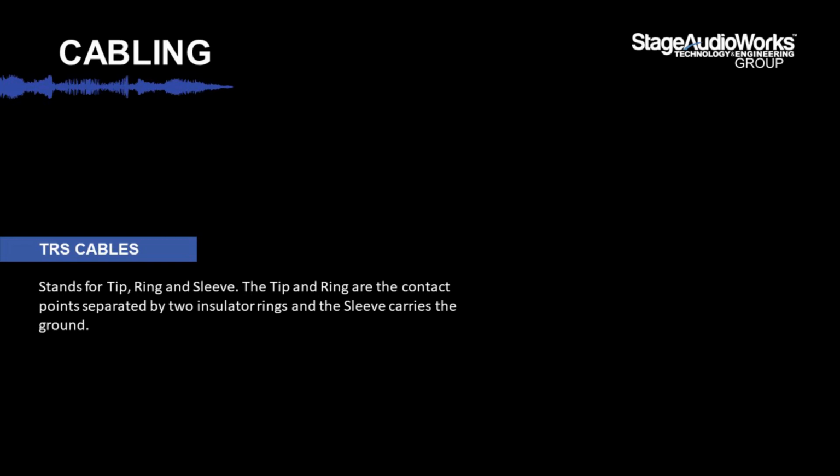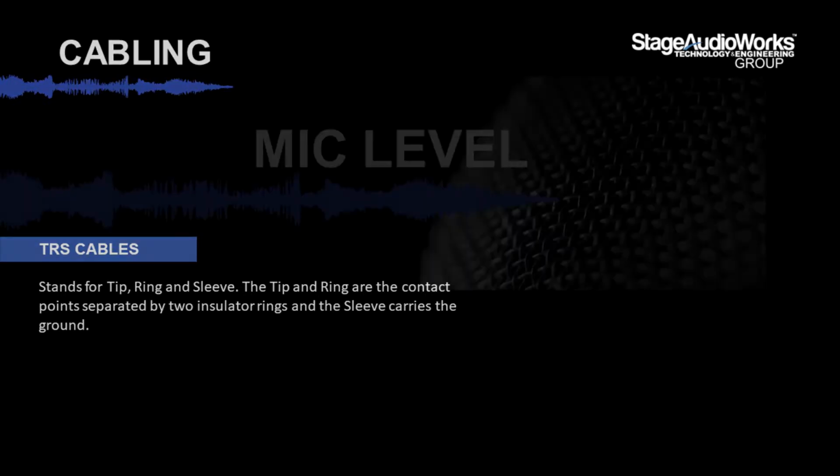Now, before we carry on, there's something important to discuss, and that is mic level and line level, as these are going to pop up again. Mic level describes the voltage generated by a microphone when it picks up sound, and this is typically a few thousandths of a volt. So this voltage varies in response to changes in voice level and in the speaker to mic distance, but the signal is still quite small.